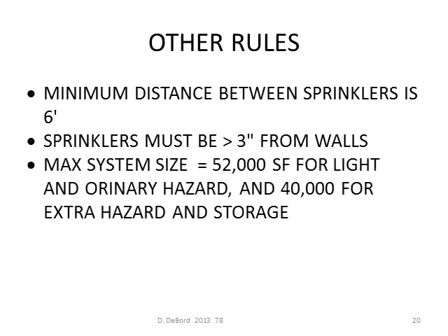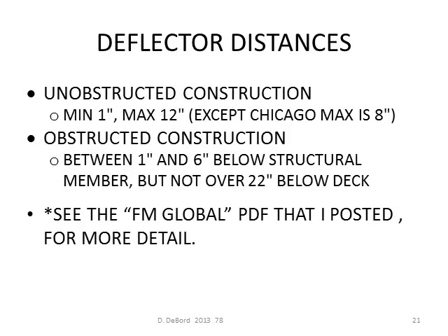Maximum system size is 52,000 square feet for light hazard or ordinary hazard, and 40,000 square feet for extra hazard and storage facilities.